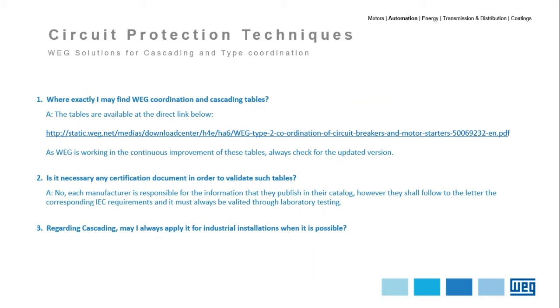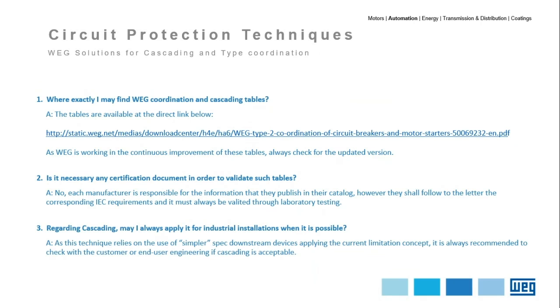Regarding cascading, may I always apply it for industrial installations when it's possible? As this technique relies on the use of simpler spec downstream devices applying the current limitation concept, it is always recommended to check with the customer or the user engineering if cascading is acceptable.